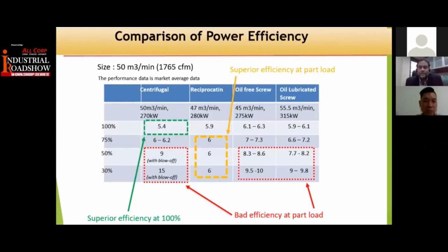So you must have a mix of compressors, where you have a centrifugal compressor as your base compressor, and your variable speed drive as your top-up compressor. It is the wrong way of doing things to get rid of your centrifugal compressor and just put in a variable speed drive compressor. The saving is not much if you run a variable speed drive compressor at a very high output.